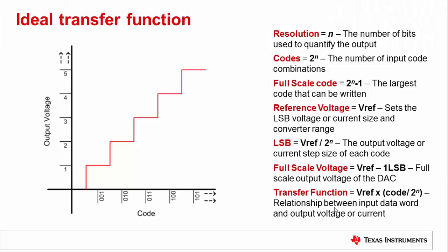When beginning a study of electronics, one of the first things any engineer is exposed to is the ideal op-amp. Understanding the properties of the ideal operational amplifier helps simplify circuit analysis, but also gives great insight into what causes error in practical op-amps. Similarly, we should establish a model for the ideal DAC before exploring where errors are introduced in practical DACs. The first and most basic parameter for any data converter is its resolution.